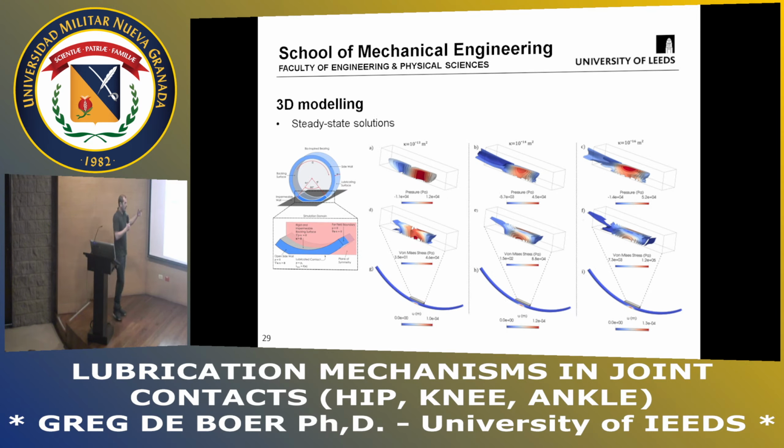So that was a bit of the work that we did with 2D models, and then that's been advanced towards this type of problem, which is a bio-inspired bearing. This is some work I did with Imperial College in London. And really what they were trying to do is design a bearing that has this same load carrying capacity. We used exactly the same techniques, but we've expanded it into 3D. This is using a different bit of software called Phoenix, which is an open source finite element code.